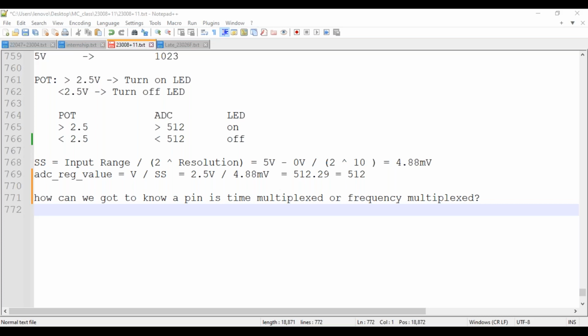Madam, can we use two channels together for ADC conversion? No. As we discussed, there can be only one channel active at a time, as there is only one register to collect the output of the ADC block. If you use two channels, it may give two different 10-bit digital values, and you cannot store them in a single register, you would need multiple registers. There are in fact two, a low and a high register, but they can store only one digital value at a time. So there can only be one channel active at a time.